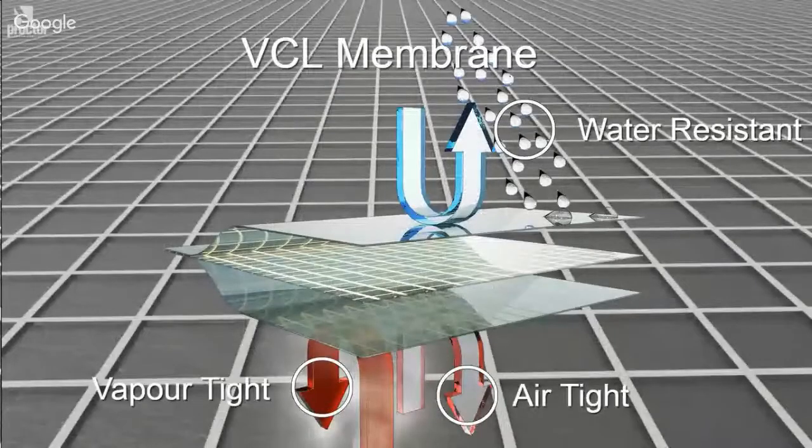The good news is, in comparison to the breathable membranes, vapour control layers are relatively simple. Most vapor control layers are polyethylene or aluminium, and none of them have perforations. And that ensures that the vapor resistance and airtightness of the product is maximised. When it comes to vapor control layers, reinforced membranes are generally preferable. So basically, the performance of the membrane is only as good as its continuity. Unreinforced membranes can tear and stretch unless care is taken during installation.